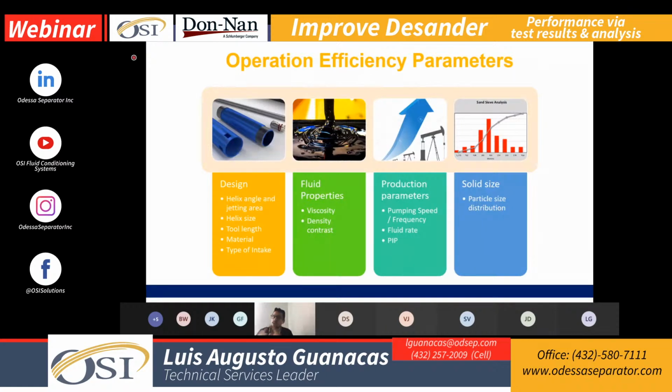Okay, well, we will cover this part later, but that has more to do with the size distribution of your sand, right? In that section, Chivan is going to elaborate more, but just to give you a heads up, big and fine particles play an important role in this separation matter. But this is a parameter that we can hardly control. Nowadays, all the companies are using 100 mesh, maybe 30, 50 frac sand, and this size is going to play an important role in the dynamics of the separation in this tool. Okay, so you'll adjust depending on the solids then. Right. Yes, we need to.